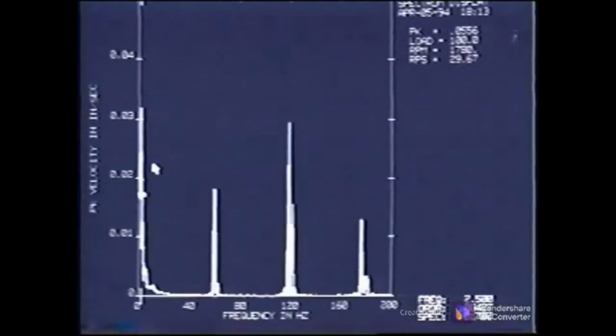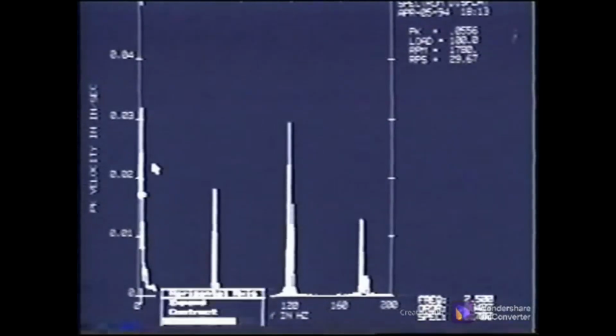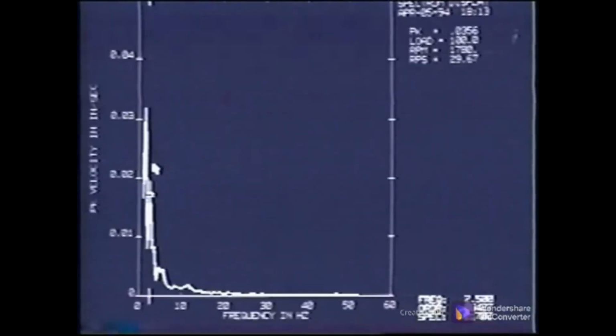The spectral data from the 200 hertz data has 400 lines of resolution, but includes energy down to 1 hertz. The 2.5 hertz is very low in amplitude and will typically be overlooked. However, this low-frequency event is observed in the spectrum. The cause of this frequency is discussed in the next section entitled Modulation.